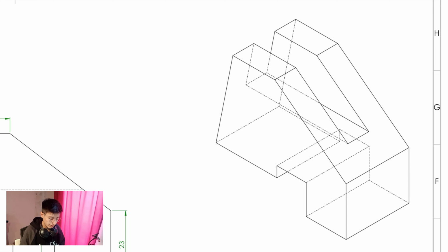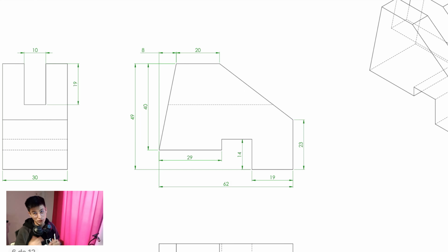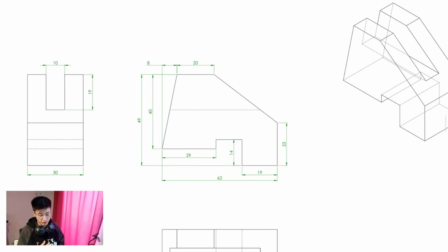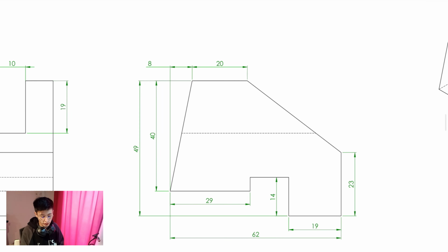My apologies. Now, as always, we need two things. The first one, the unit system that the engineering drawing is using, because we are going to take into account engineering drawing information. So we have to know if it's working in millimeters, inches, feet, whatever. In this case, and this is something that I'm going to discuss at the end of the video regarding some things about the engineering drawing topic, we don't find that information. So we are going to assume that these are millimeters. We're going to work in millimeters.